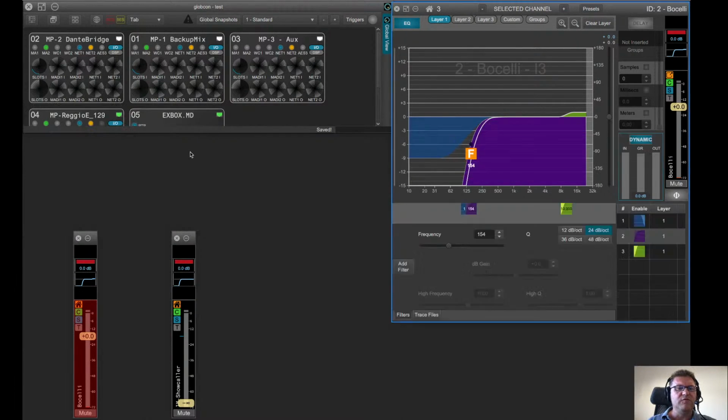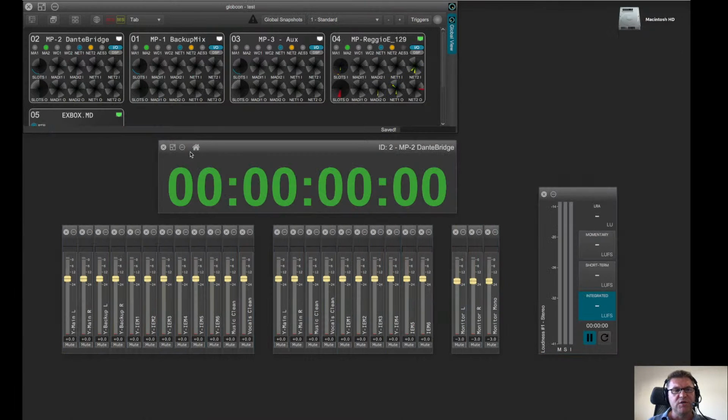Then I had the normal feeds. If the console was in charge, and it actually was, the Prodigy set was just the one collecting all the feeds from the microphones, converting them towards the console, and getting back from the console the several feeds to feed the broadcast: Yamaha main left and right, Yamaha backup left and right, Yamaha in-ears from 1 to 6, music clean and vocal cleans, and the analog versions of that, plus the 3 monitor monos and the monitor left and right. And remember, the LTC was fed directly from Pro Tools with all the redundant aspects